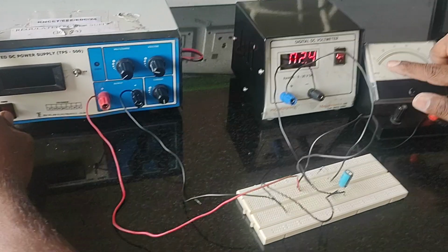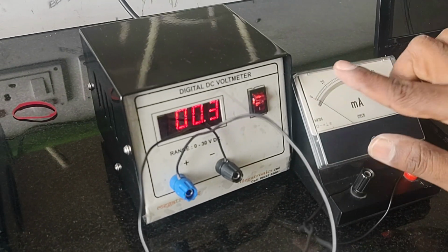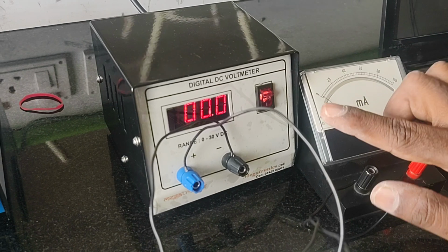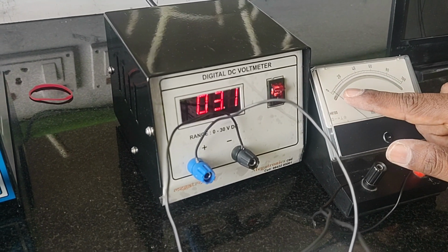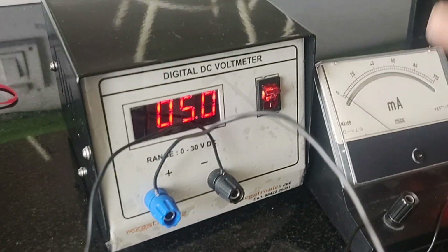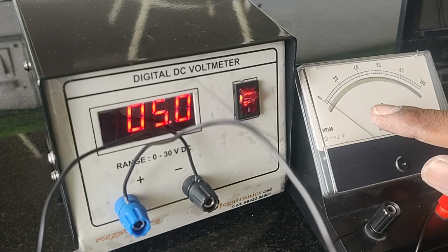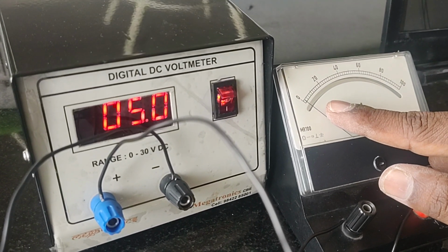So we will check this. The ammeter tends to negative because the discharging current will flow. That's the thing, that is where the discharge takes place. After entire discharging, when you supply the voltage, the current becomes 4 milliamps. Then it will take 6 seconds to reach 0. For each second, we have to take the corresponding voltage value, then the ammeter value.